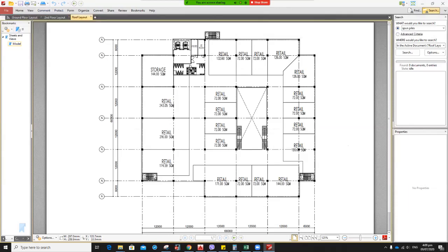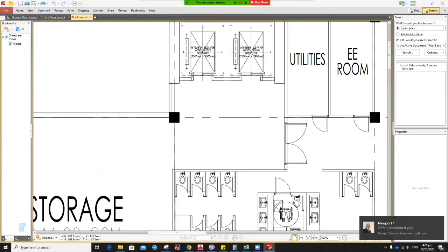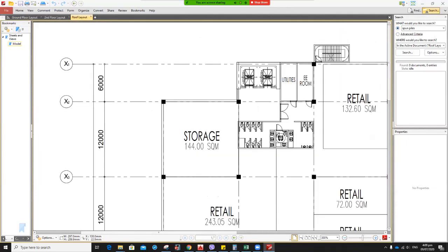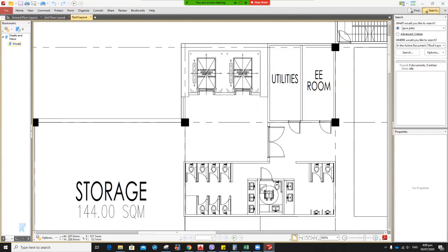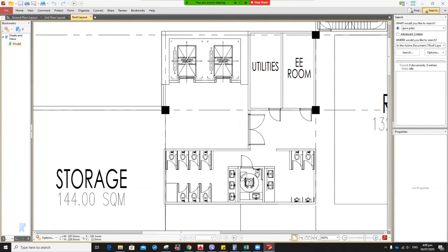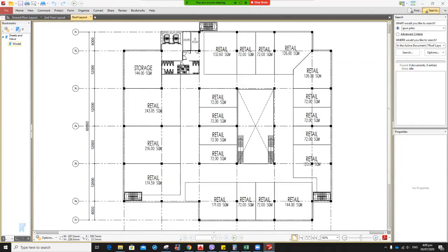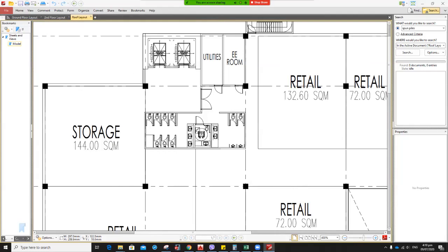So since you already have the column system, this one, then we have here a shear wall. This is a shear wall or a concrete wall that is prepared by the architects. We have an elevator with concrete wall, okay? But we can change it. Okay, we can always change it. The most important part is that it should be a concrete wall. Doesn't necessarily we need to make it a shear wall because it will just make the system rotate because it will be very, very rigid in this point. So it will be like a pivot. So to remove that, we can just put another column here.